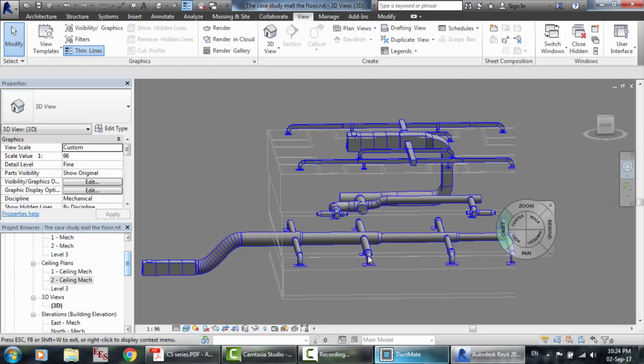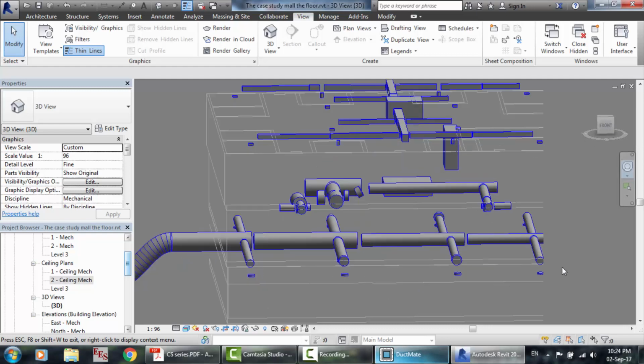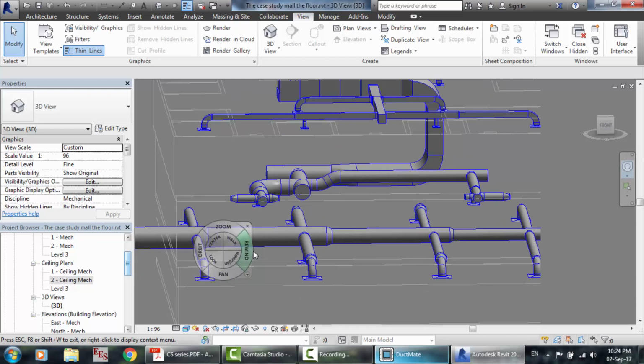Notice that this branch is very amazing, but you have to know that you can generate the layout automatically, but then quickly modify the duct sizing and the connections. Okay, to avoid these problems, you have to know exactly the offset of the duct and the offset of the diffuser.